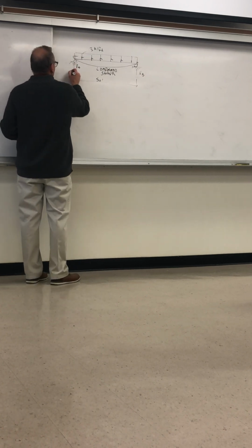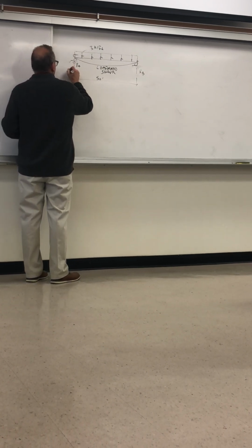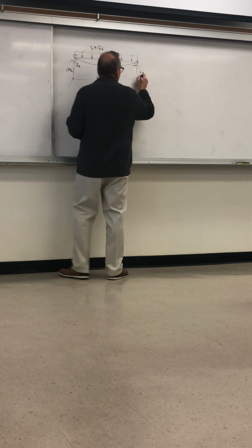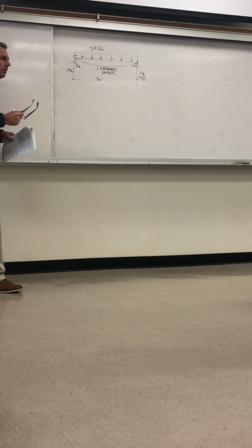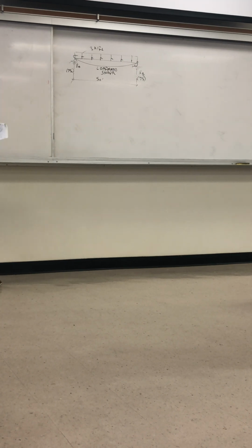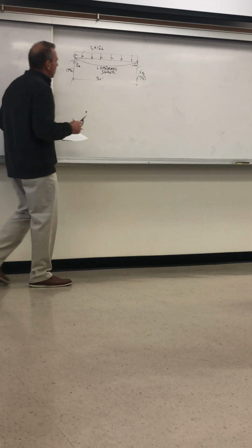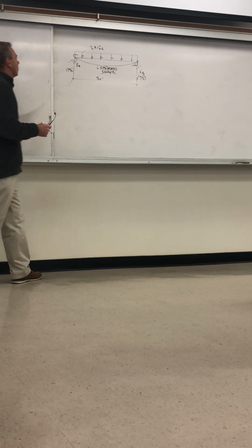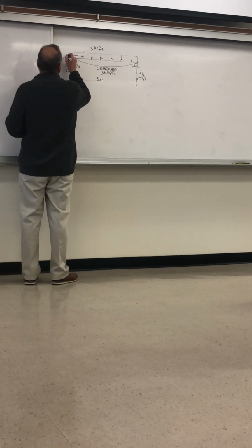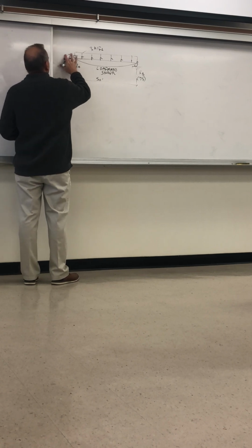So this is 75 kips. 75, because the loading is symmetric, it's an evenly distributed load. The total of the reactions add up to 3 times 50, which is 150, divided by 2, and that's 75. Those are our reactions. In this case, as often, there's no longitudinal reaction.